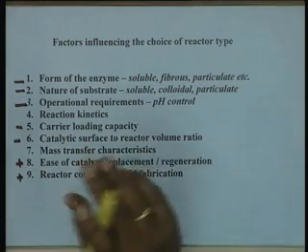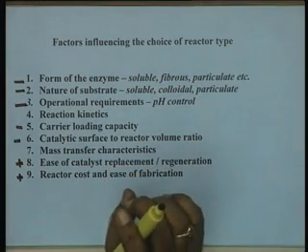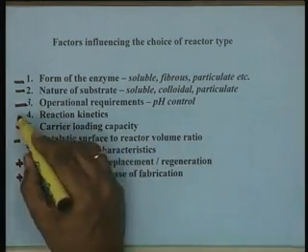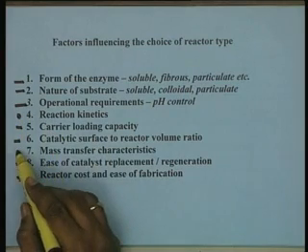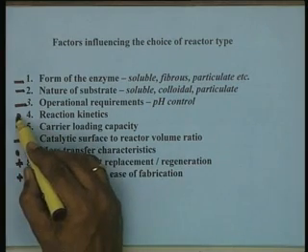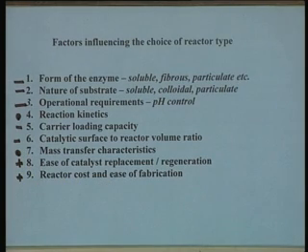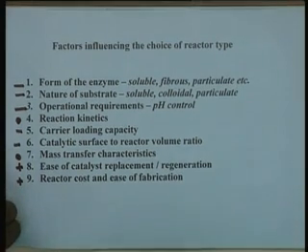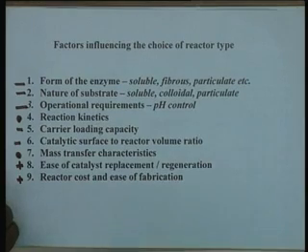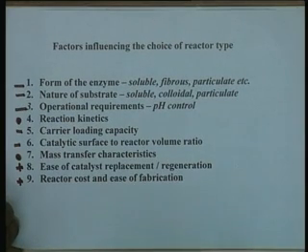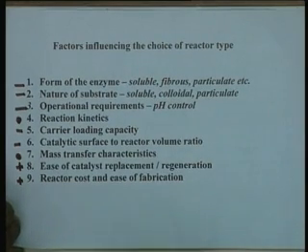But the two important class of factors which I wanted to point out here, one is your reaction kinetics and mass transfer characteristics. Now, they are the ones which very heavily dictate the choice of the reactor, whether to go for a plug flow reactor or to go for a batch reactor or to go for a continuous stirred tank reactor. They are very heavily dictated by mass transfer requirement and reaction kinetics.